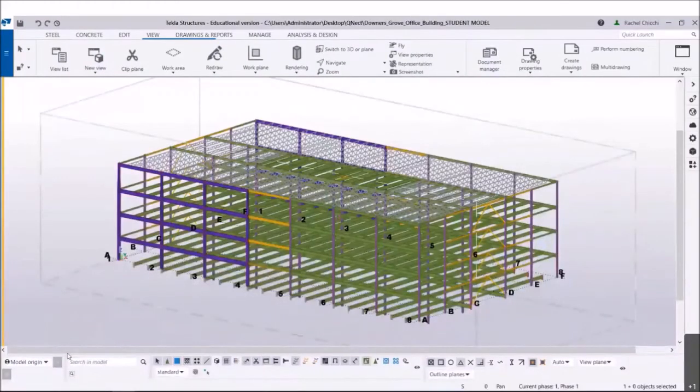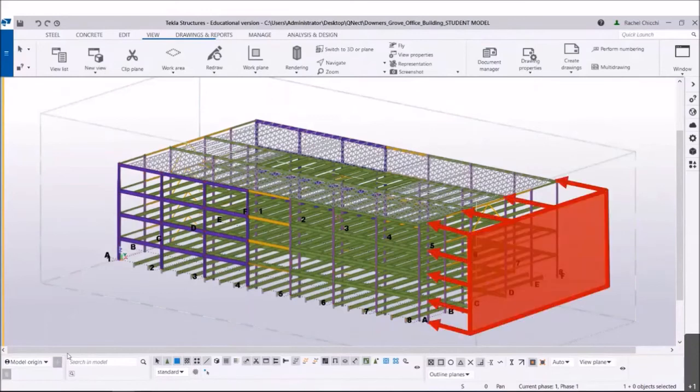Finally, the model doesn't show the floor slab, but we typically use a concrete slab on metal deck for steel-framed buildings. This floor slab provides a surface for people to walk on and for the gravity loads to transfer. But the floor is also a way to transfer lateral forces to the lateral system. If you think of wind hitting the side of this building, the wind will hit the exterior walls, transfer to the floor to each floor level above and below, and then transfer through the floor until it gets to the moment frame structure and ultimately down to the foundation.